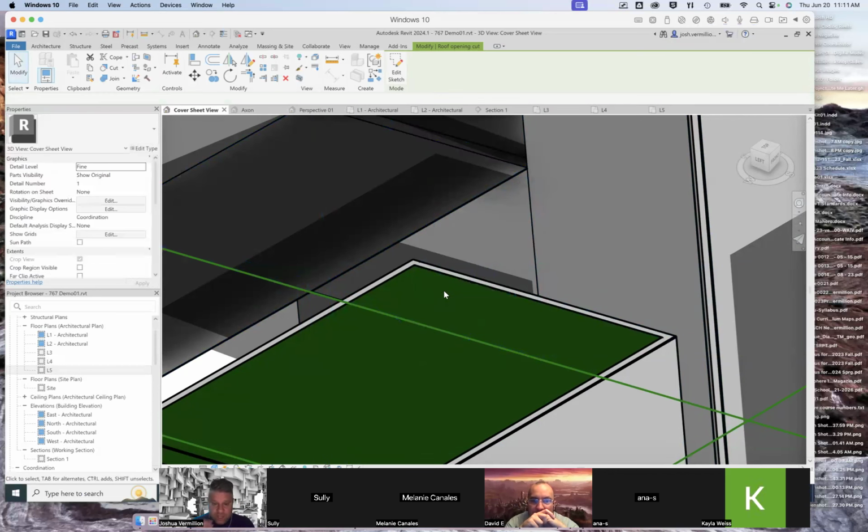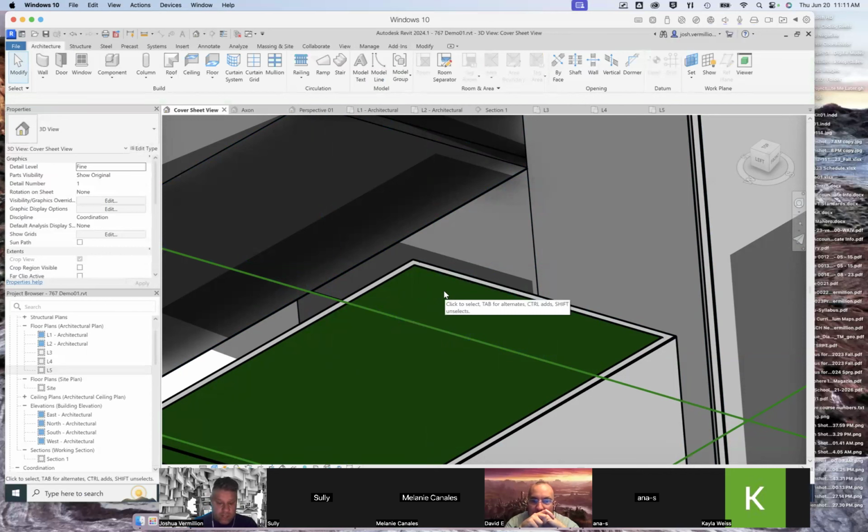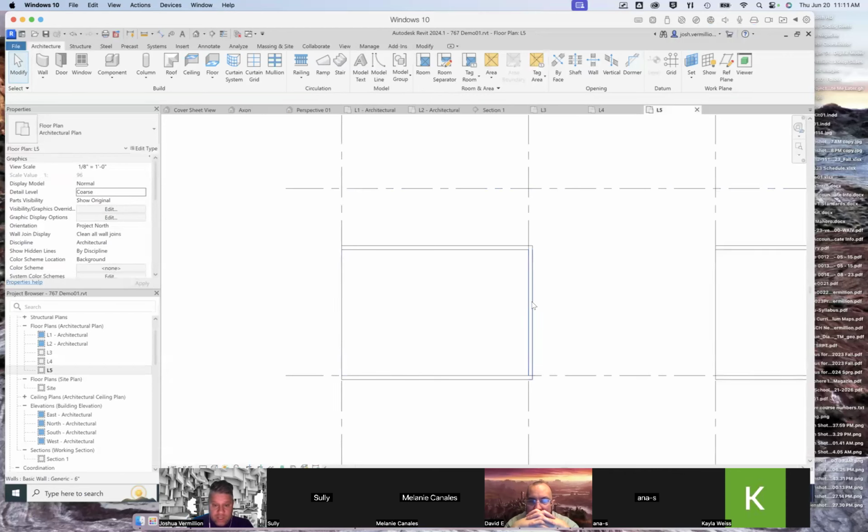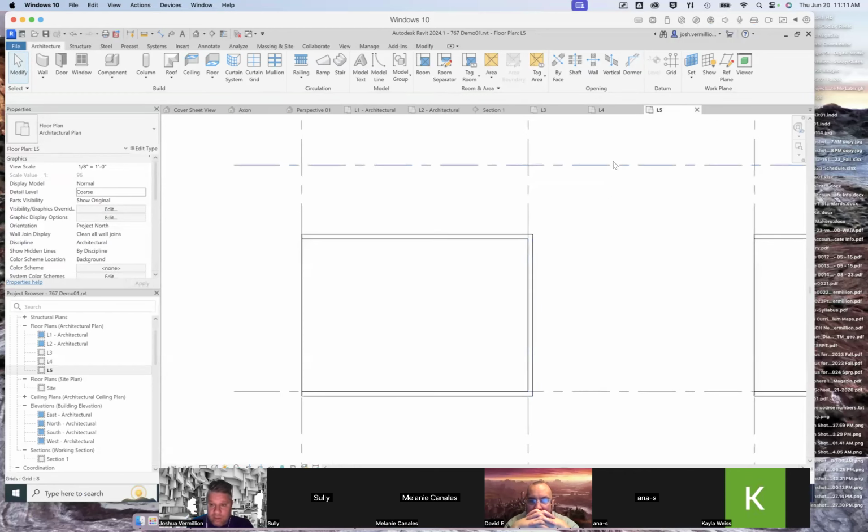Of course, if I just delete it, it goes away, right? So you can have invisible geometry cutting holes through things that you can simply delete or redraw, right? So let's try this one more time and see if I get something a little better here. One of the things I can do is go to plan view, and it's a lot easier to draw orthogonally there, right?